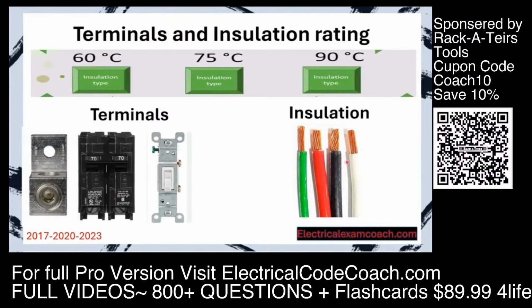And the insulation has multiple ratings. Some of them are rated for 60, some of them are rated for 75, and some of them are rated for 90. The reason this is important is it's going to help us choose which one of these columns we select our ampacity from. If the terminals are rated 75 degrees, we're going to choose the 75 degree C column most of the time. I'll explain what most of the time means later in the program, because this section is